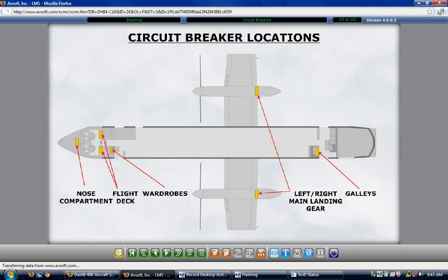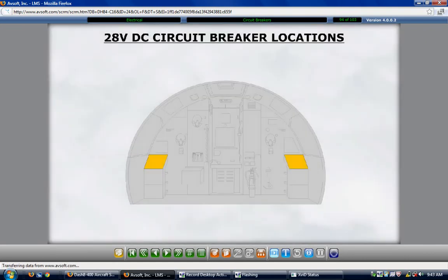2 contactor boxes are located in the aircraft nose compartment upper section. The first is the DC contactor box. It provides the control and distribution of DC power sources, those being the DC generators, TRUs, the main and auxiliary batteries, and DC external power.